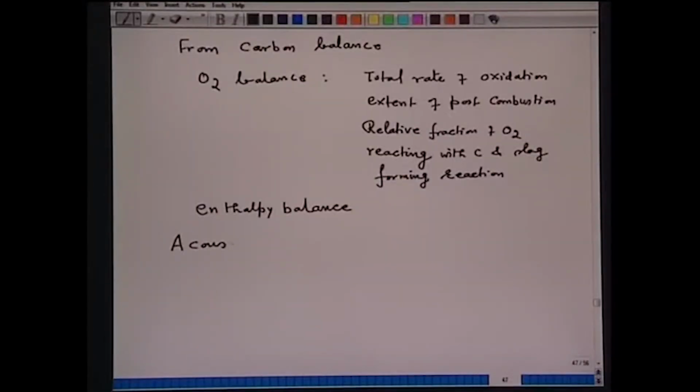Now, another online measurement that can be done is the acoustic noise. In LD steel making, the acoustic noise results from slag volume and emulsion in the slag. Emulsion is the dispersion of metal droplets in the slag. The greater the slag volume, the higher will be the acoustic sound. So, from the level of the acoustic sound, one can exercise the control.